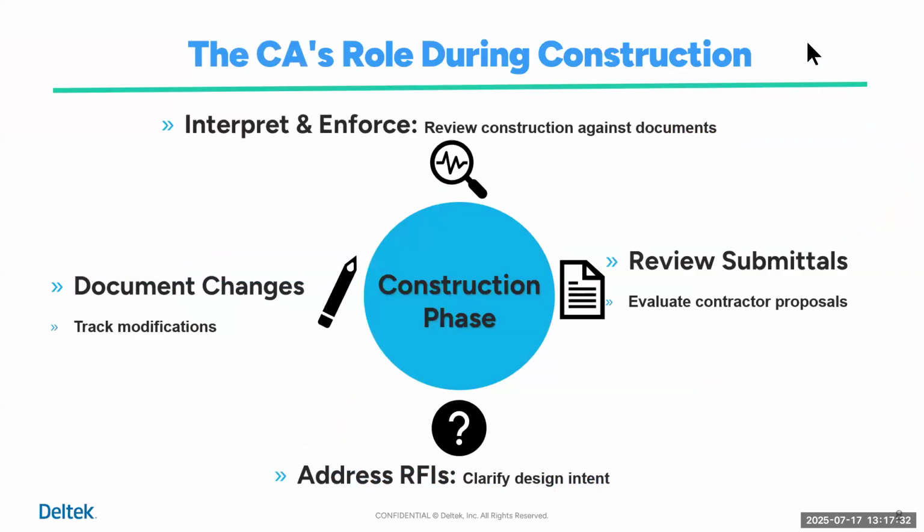Well, during construction, the CA person can enforce and interpret by reviewing construction against the documents. Also, document changes that may come up, review submittals. These things are all important when it comes to the during construction phase, answering questions in regard to RFIs and any other questions that may come up during construction. Well, that's the role of a CA during construction.